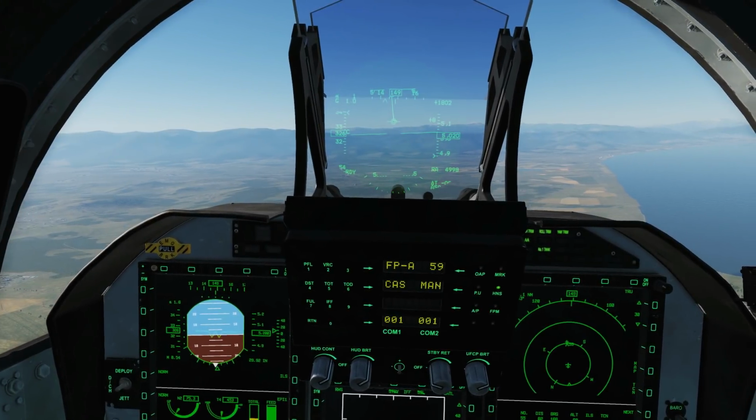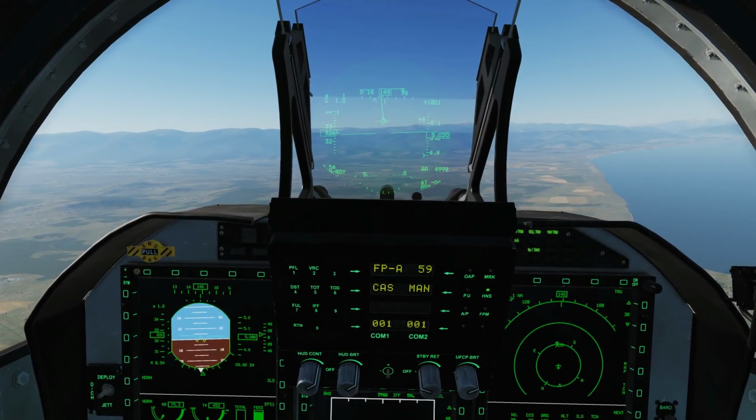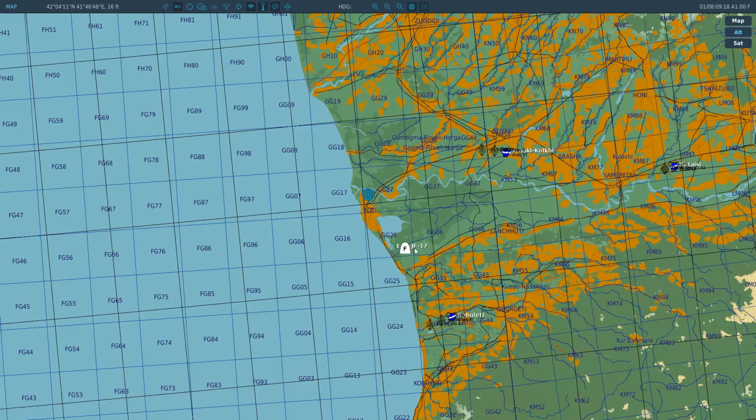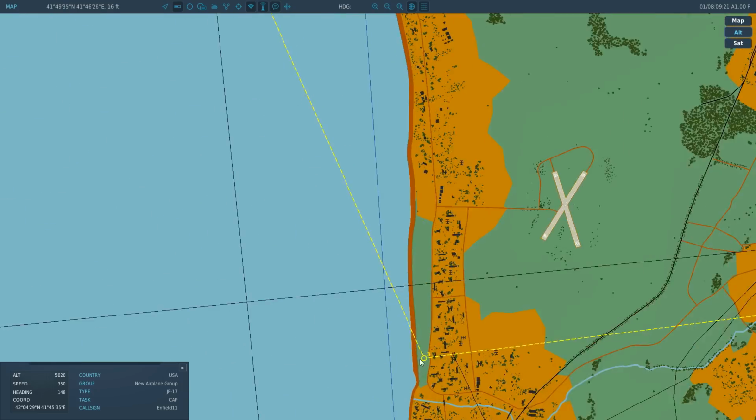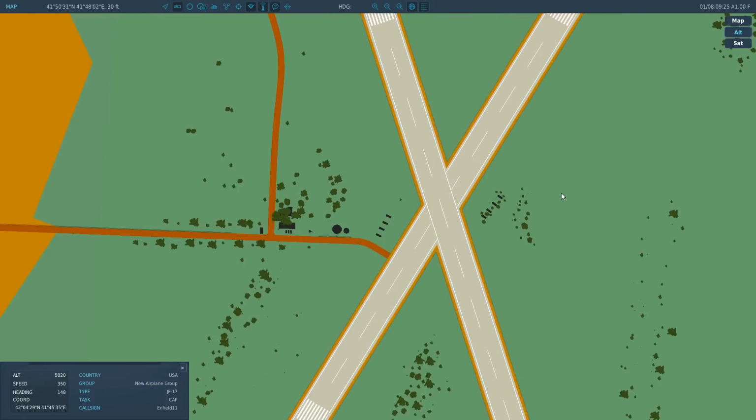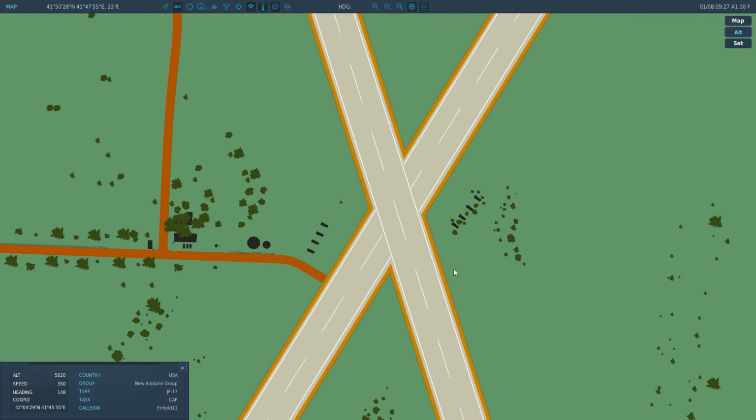The next thing I'd like to show you is how to modify existing waypoints. Remember, waypoint 3, which is there, is off target. I want to put it there. So the first thing we're going to do is get the lat long of the cross. So now I'm going to turn that to 8-digit. I'm going to plonk it there. Look at the top left. I'm going to write that number down now.